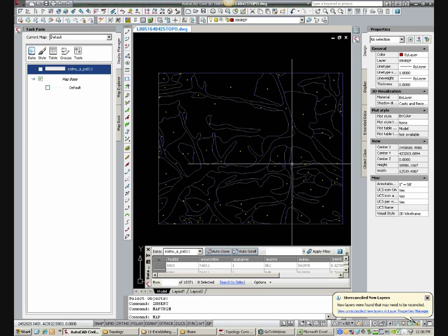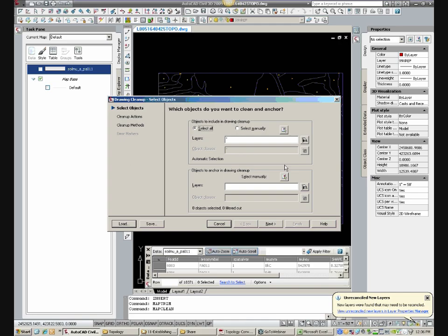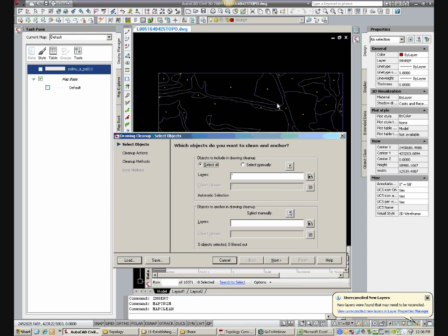So I'm going to type another command called map clean. This is just a workflow process. Watch the video to follow again or replicate it. When these soils are brought in, they're closed polylines, and they're overlapping each other on the edges. Very similar, and it's not coincidence, to Civil 3D parcels.